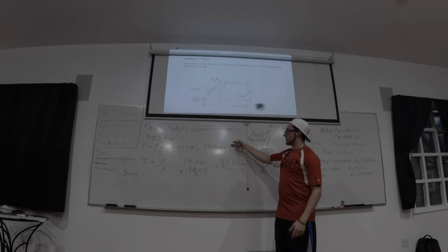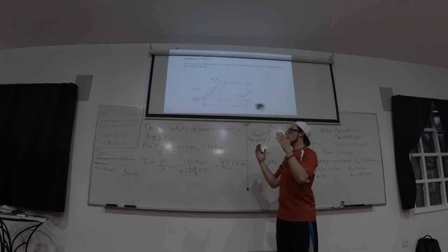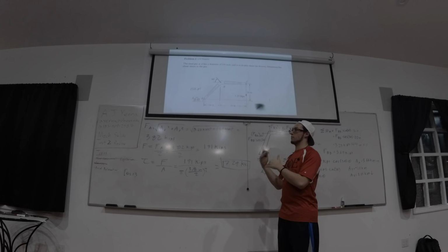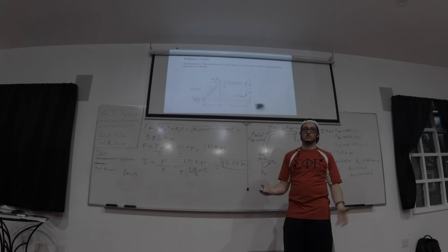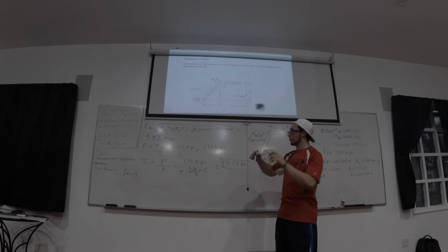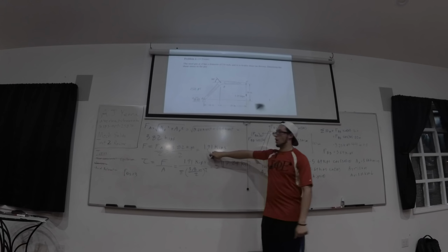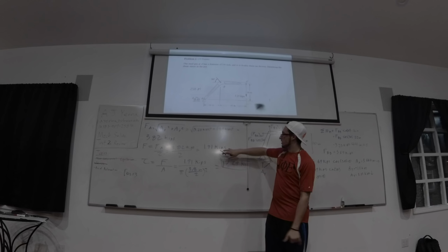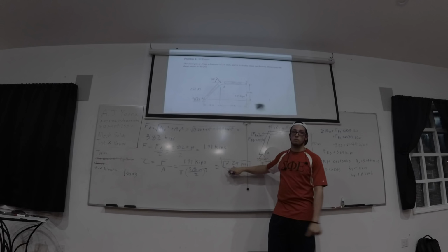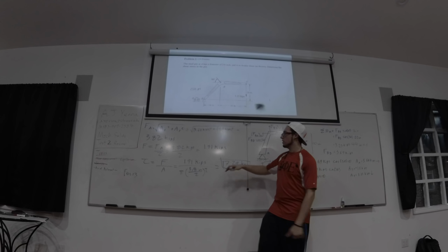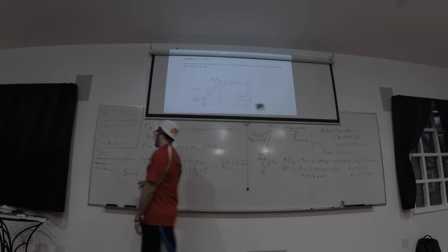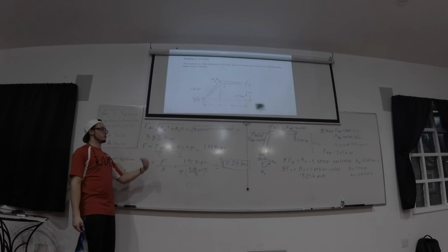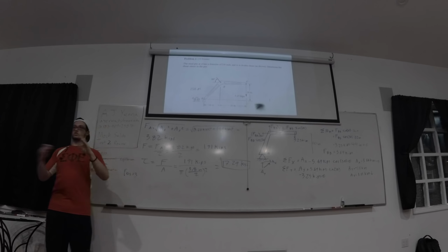And the question was worded as what is the highest amount of force you can design this thing to withstand. You have to say that it can only actually withstand 1/3 of this force. That way you're designed for the safety. This 1.91 kips will essentially break the pin if this is your maximum. So you kind of have to back design it, but just remember that this factor of safety will decrease the force. Is there any questions on that?